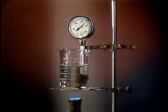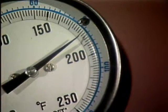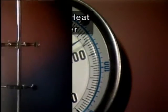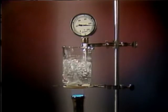A temperature change can be measured or felt. Heat transfer that causes a temperature change is called sensible heat transfer. Heat transfer that does not cause a temperature change is called latent heat transfer. During latent heat transfer, there are changes in molecular energy, but these changes don't result in a temperature change. Instead, they result in a phase change. The three phases or states of matter are solids, liquids, and gases. So, sensible heat results in a temperature change, while latent heat results in a phase change.